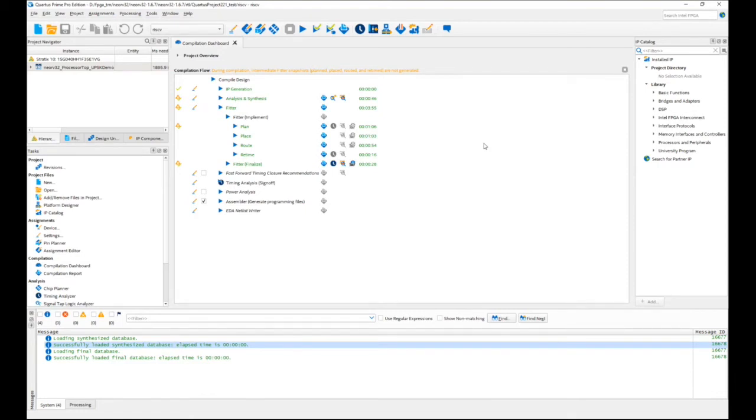I don't know if it's a bug. It sounds like they could be using, like you said, a licensed IP. So if there's a licensed IP in their design, that could be what's going on there. It's weird that it's when they're using the timing analyzer though. The fact that it's coming up with an error in timing analyzer saying license required is odd. If it were a licensed IP, I would expect that error to come up in another place and not timing analyzer.